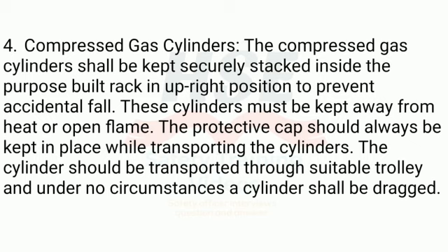4. Compressed gas cylinders. The compressed gas cylinders shall be kept securely stacked inside the purpose-built rack in upright position to prevent accidental fall. These cylinders must be kept away from heat or open flame. The protective cap should always be kept in place while transporting the cylinders. The cylinder should be transported through suitable trolley, and under no circumstances a cylinder shall be dragged.